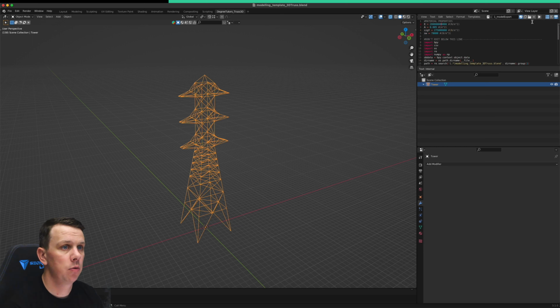In this one, above the dashed line, we can set a Young's modulus, a cross-sectional area, yield stress, and self weight. That will apply those properties to every element within the structure. If you want different properties for different elements, the best way is to dive into the CSV file and edit manually in there. It's very doable, not too hard to do, but I'm not going to focus on it in this tutorial. I'll just apply those default properties. There's nothing to it. All you have to do is hit that play button there.